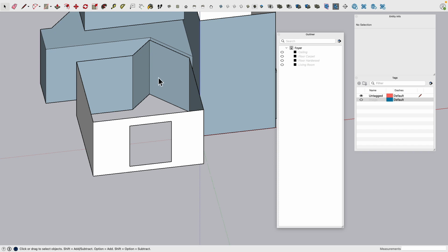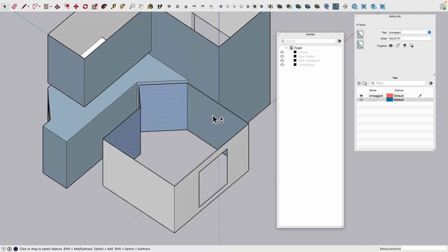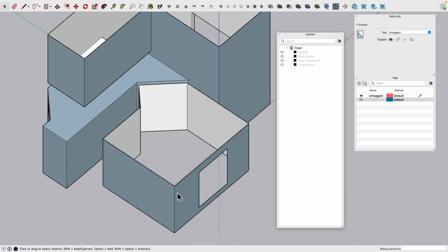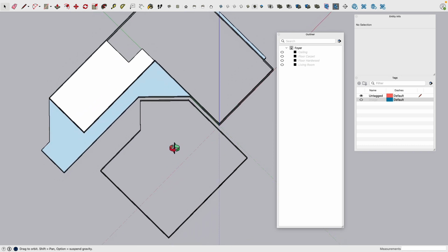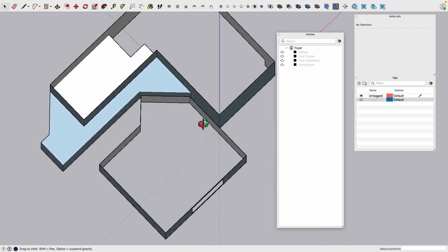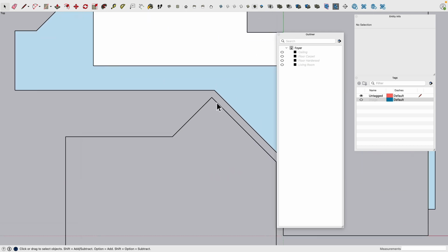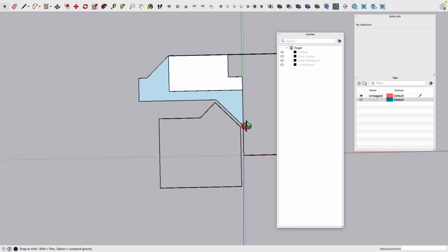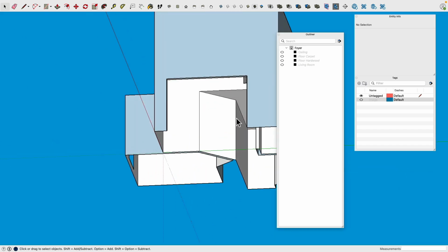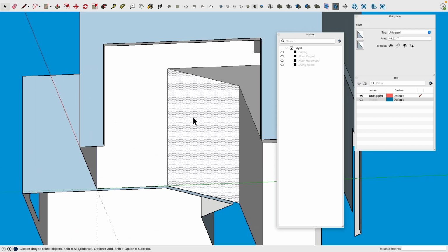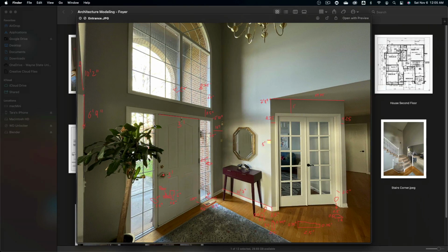This here for the moment I open too, so we can look into it. All these faces are wrong. Right click and reverse face. Very good. Beautiful. Okay, let's hope that this for the moment is actually good enough. Oh no, this should be all good. Okay, so I think at this point we are ready to do our first task for the detailing, and that is to cut in this opening here.